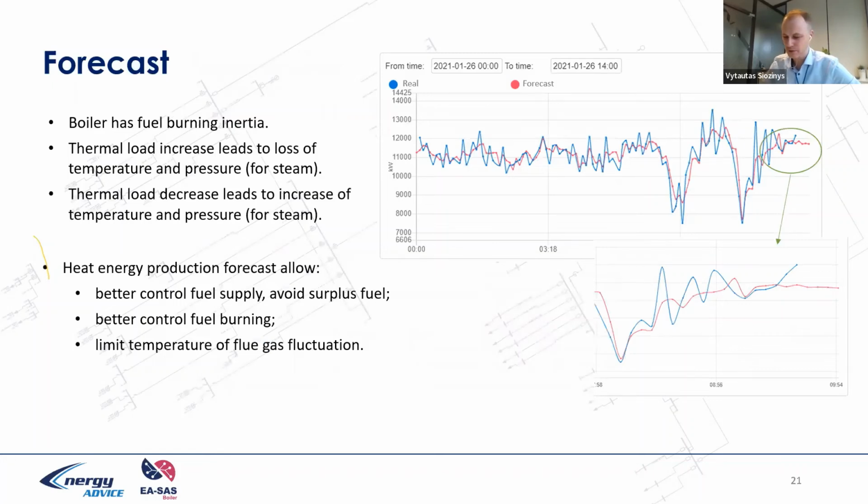When we do smart control of the boiler, in the very short term we can make a real forecast of the boiler loading, thermal loading. And why is it important? Because the boiler has fuel burning inertia.